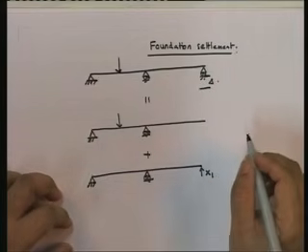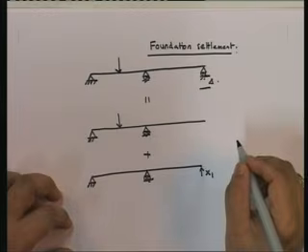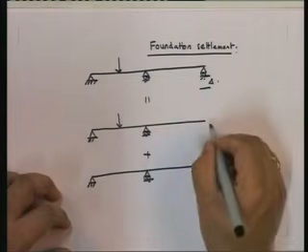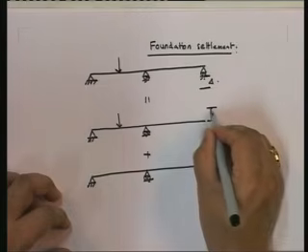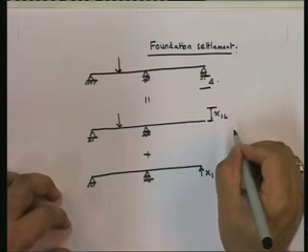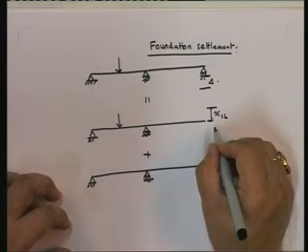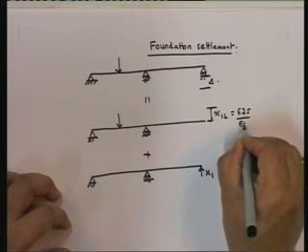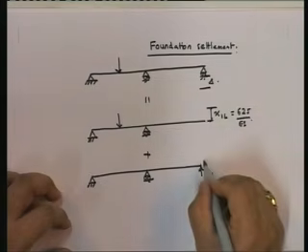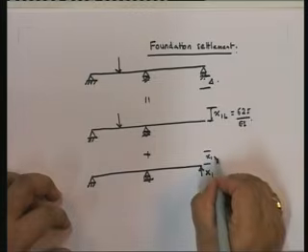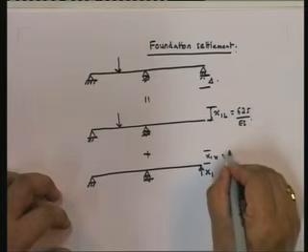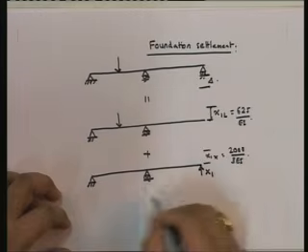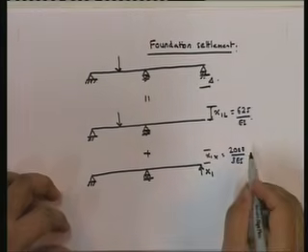So now here, what are we getting? We find out x1L. Note that this x1L is going to be the same as before, so this is going to be 625 upon EI. We're going to find out x1S, and this again is going to be the same, so it's going to be 2000 upon 3 EI, because there is no effect over here.